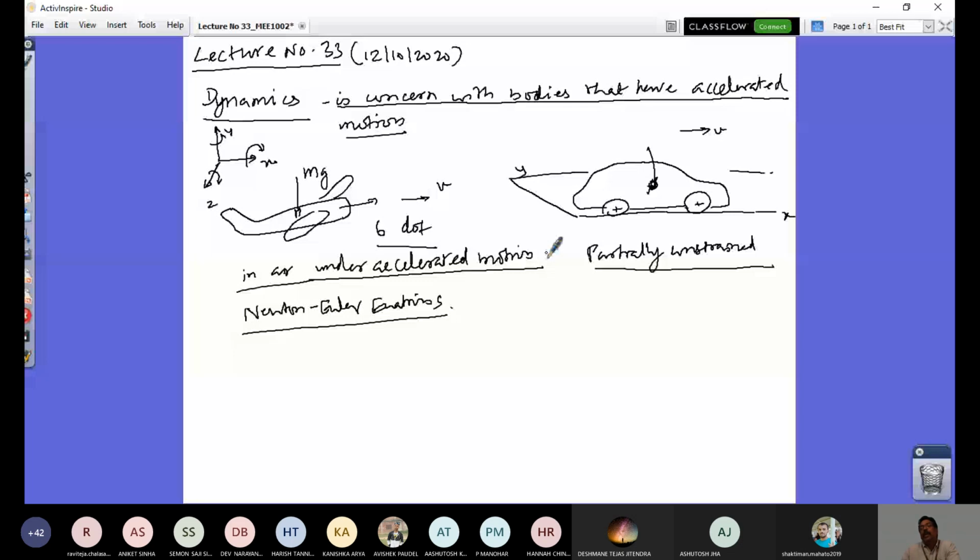Even a body which is constrained partially can have motion only in this direction, or in this lateral direction, or it can spin about its axis. Yaw motion it is called. So it can have 3 degrees of freedom on the ground plane. So the 6 degrees of freedom reduced to 3 degrees of freedom because of partial constraint. The vehicle cannot go inside the ground or fly above, and it can only spin about the vertical axis or translate in X or in Y direction.